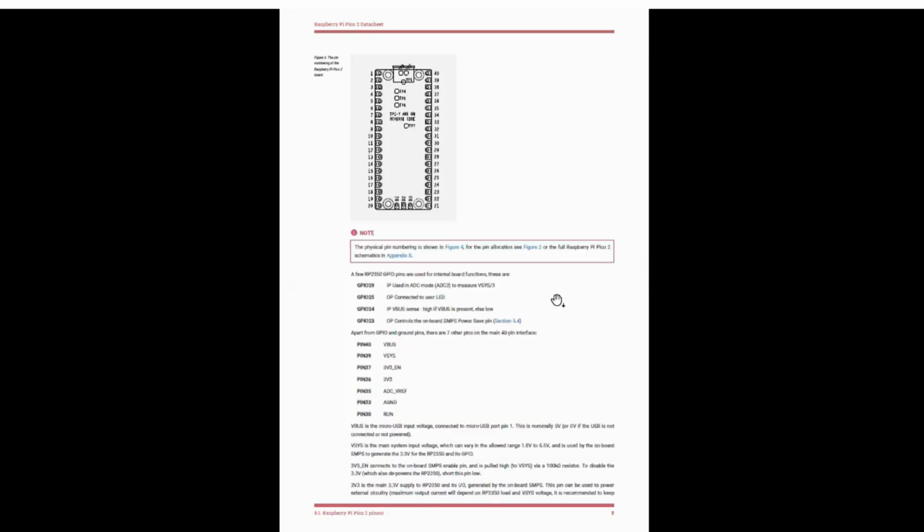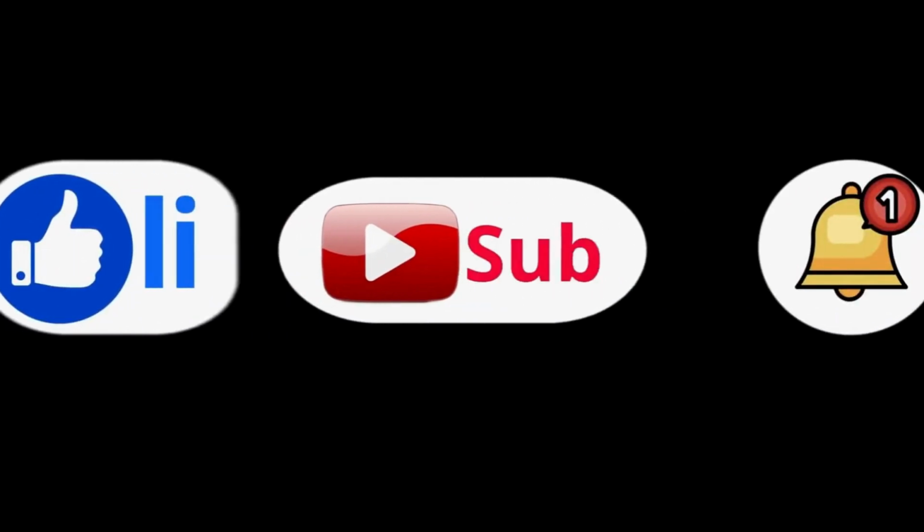You can directly see. But what I'm trying to say is, why is the data sheet important? Because the complete information you will get from the data sheet. What you have to see: features, application, package, block diagram, right? Maximum voltage, minimum also you have to check. Then current and power. These things you have to do. If you're a designer designing a PCB, then you have to see the board outline or board topologies. Okay, pin description and board topologies. These things also you should inform.